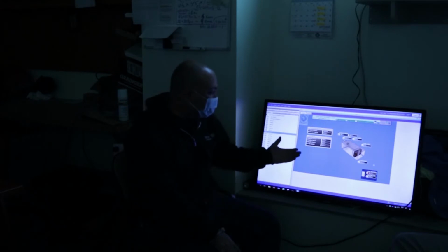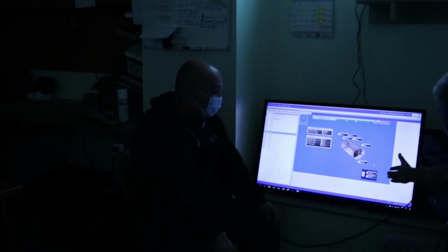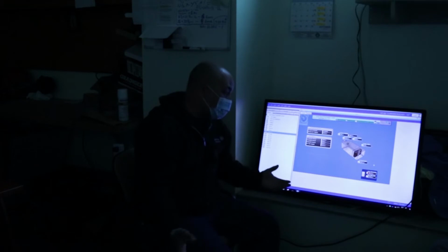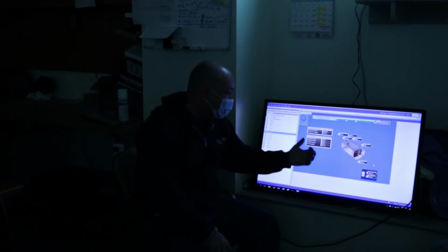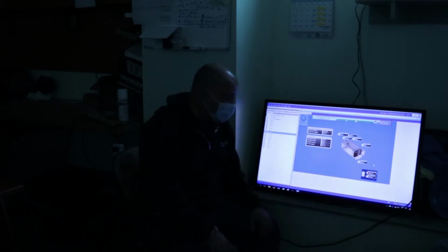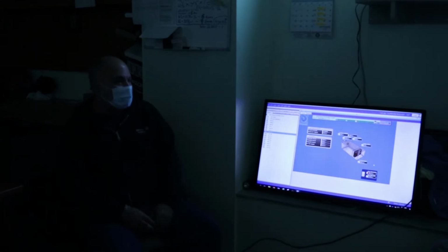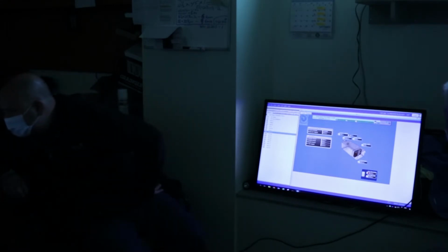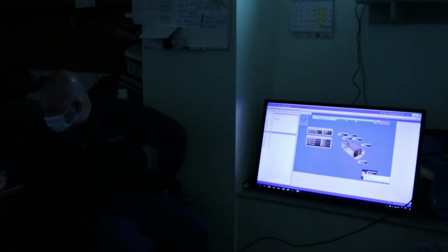But this is something we'd have to take a look at. I mean, the box, just looking at it, looks like it's working correctly. Whether it's balanced. It's working correctly if the temperature is 80, well, I'm saying it's 81 and the set point is 70, it doesn't work correct. I don't know if maybe the balancer put the wrong numbers in, or like I said, there's some extenuating circumstance that's generating heat in there. I don't know if they have some extra equipment from when they were doing the COVID up there, put into the room. I don't know what the load in the room is. What floor is it? This is the 5th floor, so 158. Well, let's put a trend in this box to see where we're at.